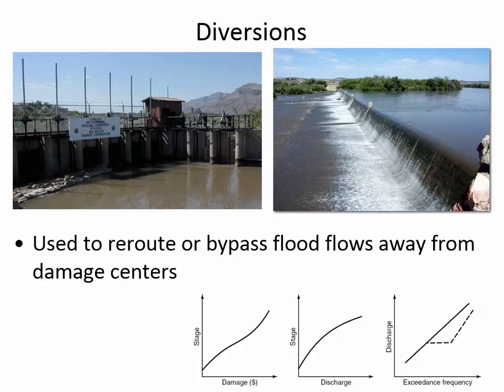If here's the river, and then you've got the town, then you could have the water go around the town by putting in some extra channel here, sort of like extra capacity. Most of the time the water is flowing this way, but when the water level gets to a certain point, this bypass kicks in, and so between the inlet to the bypass and the outlet of the bypass, the water level next to the town is kept lower than it ordinarily would be.